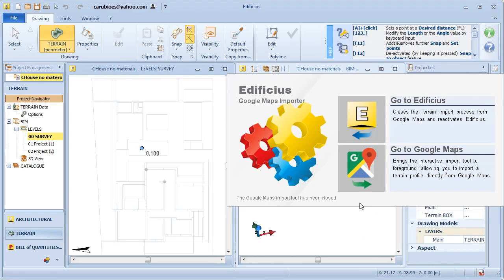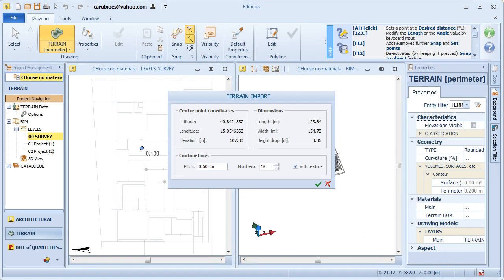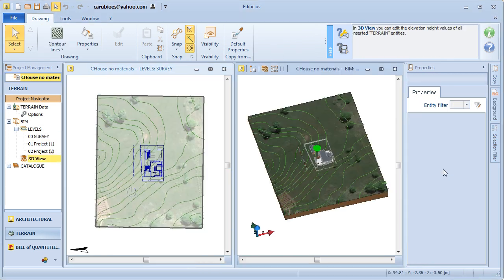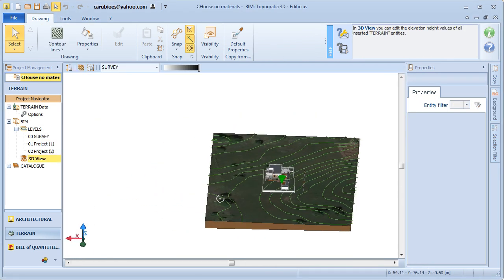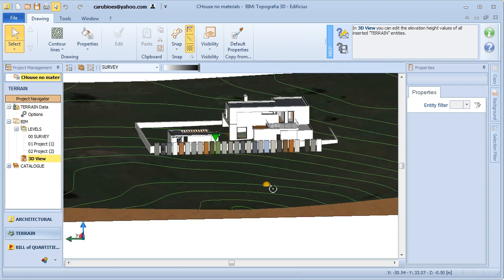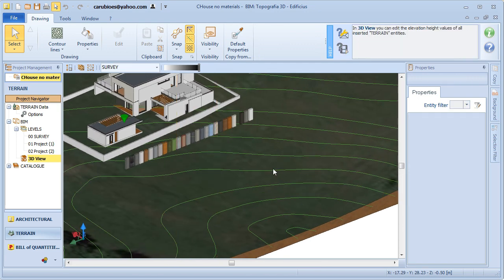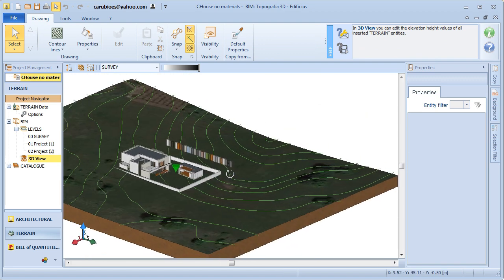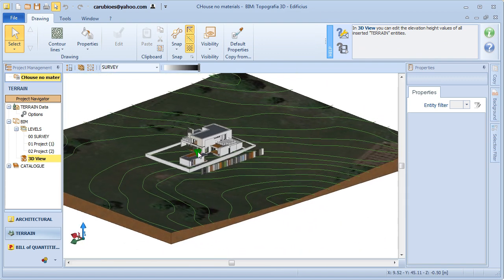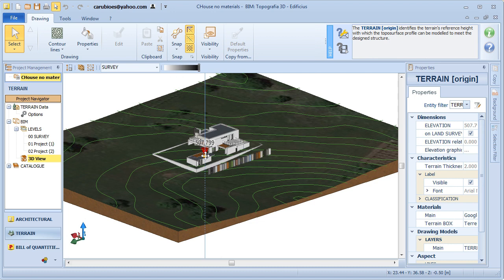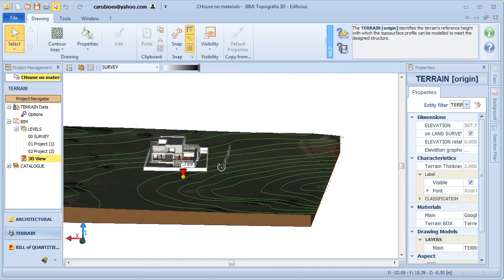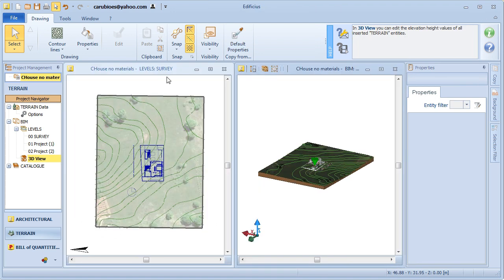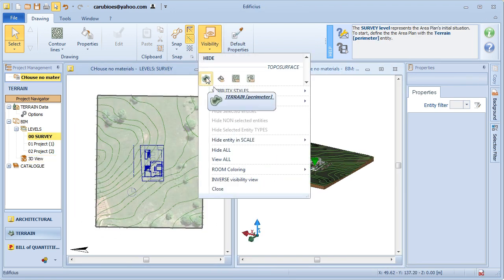Going into more detail, we can also make adjustments to align the terrain to the building, both in plan view and of course in terms of its altitude. When the object grip is activated, we simply move it into a position with known coordinates in space, and we'll then place it at a known reference point on the model.